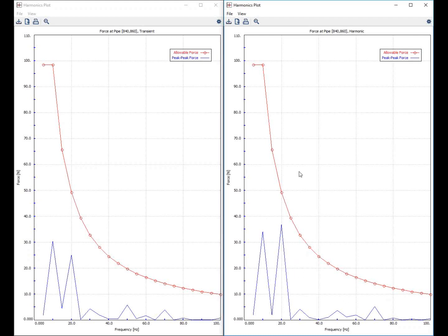We definitely recommend that you use the harmonic solver only for design purposes, where you can look at different changes in your system. So if you want to change the resonance length in your system, you can use that to quickly evaluate whether you move your acoustic resonance to a different location, or whether you add some dampening, so the magnitude also changes in different ways. And then finally do a run with the transient solver to evaluate the correctness of your solution.